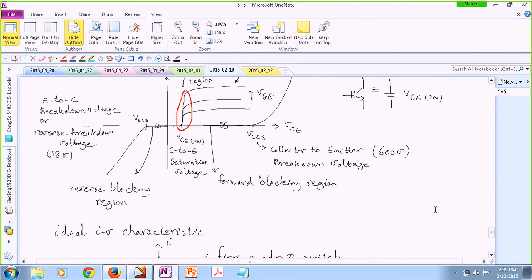So your question is, if you get an IGBT and place a 150 volt battery in parallel with that, what happens? It depends on what kind of excitation you have applied to the gate. If you have not made any excitation to the gate, you are basically somewhere around here, 150 volts. Nothing happens, assuming that your IGBT can handle 600 volts. But if you have already made an excitation to the gate and then apply that voltage, you shouldn't do that. Because if you have turned your device on, you should expect your device to conduct currents rather than applying any voltages to your device. Okay?